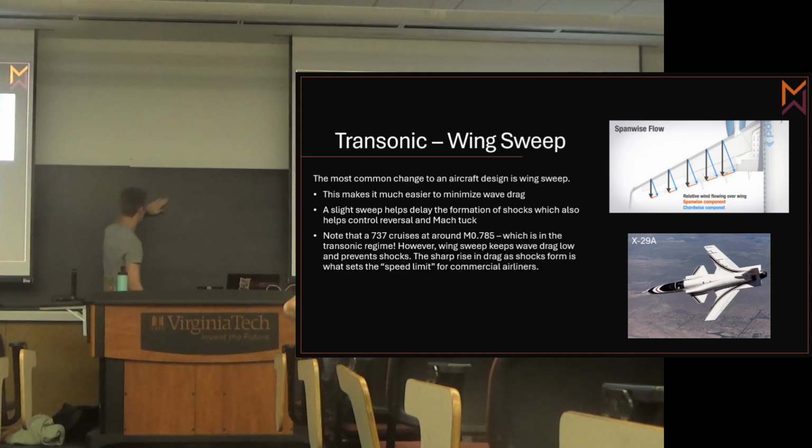However, I like to imagine if I had the same wing and it had a chord length of C here, if I sweep it here, it's still C. But as I go down to here, it's no longer C. It's this extra long version. So the thickness to chord ratio on this airfoil is now a lot lower.